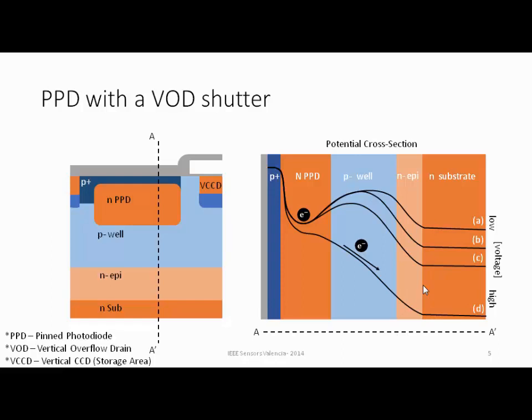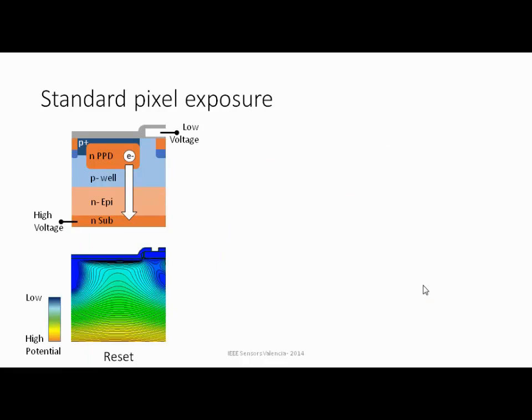barrier. When we modulate the substrate bias, the substrate voltage, we can deplete this potential barrier between the substrate and the photodiode, and then make all the electrons sweep very quickly, drift very quickly towards the substrate. It's a very well-known mechanism, but naively it can't be used for time of flight or for fast gating, because of how a standard CCD or pin photodiode pixel works.